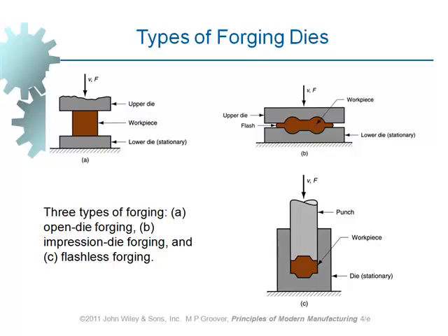Why not? It could be done several times. It could be repeated again and again until you achieve what you want. The forging process could be repeated again and again because maybe you cannot make this in one go. You've got to do a number of forging steps. So you do it, then you put it away, then you elevate temperature, subject it to another forging process again and again, repeated times until you achieve what you want.